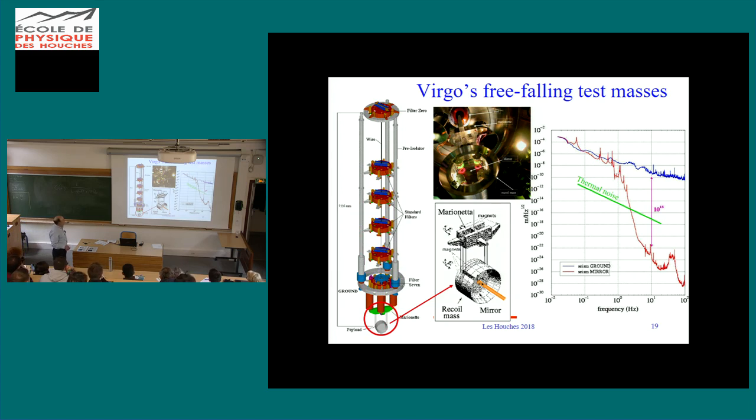And here you can see the measured input seismic noise spectrum, and I assume this must be a calculated response because I don't think no one is measuring things that well. So this is a calculated response by a measured frequency response at something that was driven at high amplitudes and then multiplied. So let me retract a bit about what I said about cascaded systems. It's not simple multiplication for the frequency region where the resonances are. You have to solve a normal mode problem there because the systems interact. But they don't interact in any interesting way at frequencies that are high compared to the resonance.